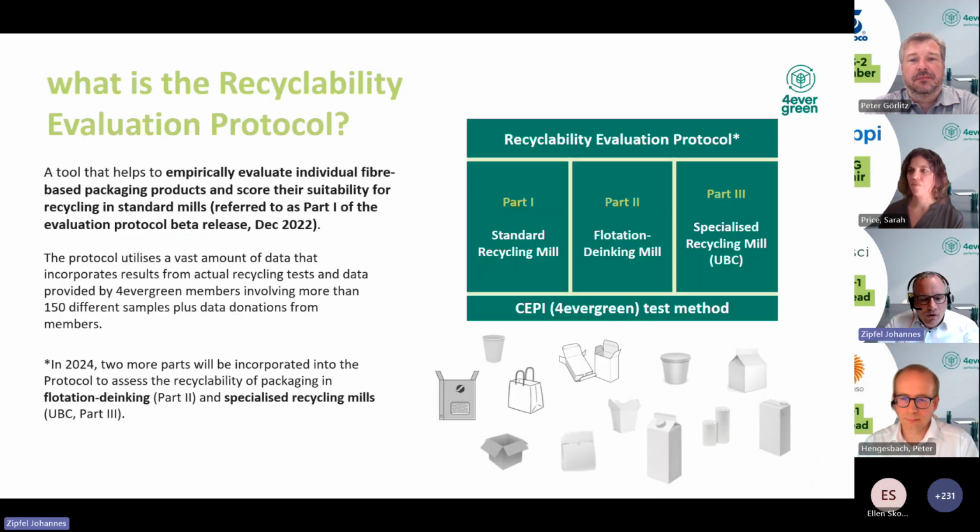The question now is, what is actually a recyclability evaluation protocol? It is a tool that helps to empirically evaluate individual fiber-based packaging products and score their suitability for recycling in standard recycling mills, flotation de-inking mills, and specialized recycling mills. There are basically two elements in it. All our testing is based on the CEPI test method, which is used by 4evergreen, but we at 4evergreen evaluate the recyclability evaluation protocol.